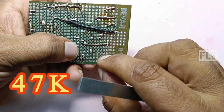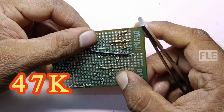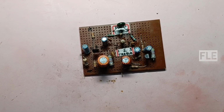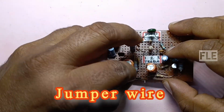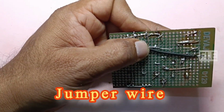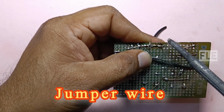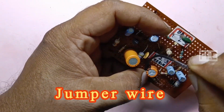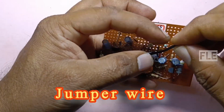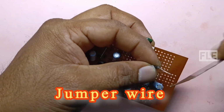Connect a 47K resistor between the base terminal and the ground terminal. Identify the base terminal of the C1815 transistor and connect the 47K resistor between the base terminal and the ground terminal. One end of the 47K resistor is connected to the base terminal, and the second end is connected to the ground terminal using a jumper wire.